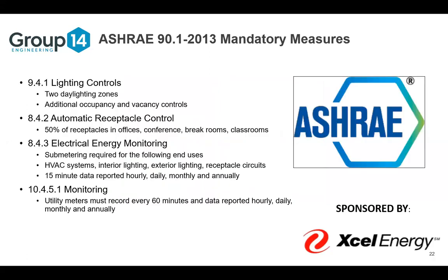There are additional mandatory measures required within ASHRAE 90.1 2013 that are not required in the IECC. And so what the IECC said was, look at all of these additional energy efficiency requirements in ASHRAE. We're not going to require those, but we are going to require either an additional energy efficiency package, that's section C406, or the 15% cost savings in section C407.